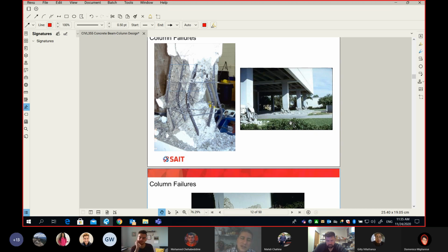But luckily, because the earthquake stopped, whatever was left of the column can still take the load. Maybe the building has no occupants, maybe it doesn't have the full design load, but I promise you, if it had the design load, with all the live load present, this building would simply collapse.